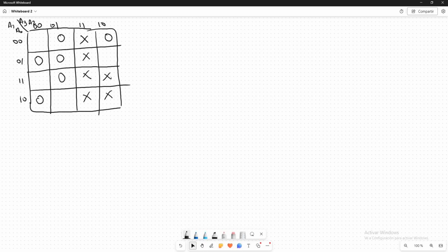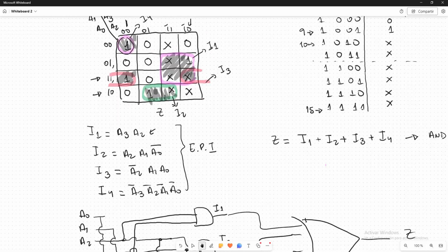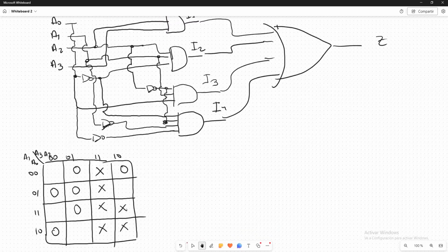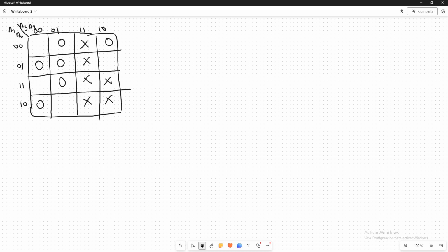So this is the same Karnaugh map as before, but just keeping the zeros and not drawing the ones. So again, we are going to look this time for the prime implicates. Remember, not implicants, but implicates. So we can use the X if it's interesting for us, remember. For example, this 0 here in the corner can be grouped using this X.